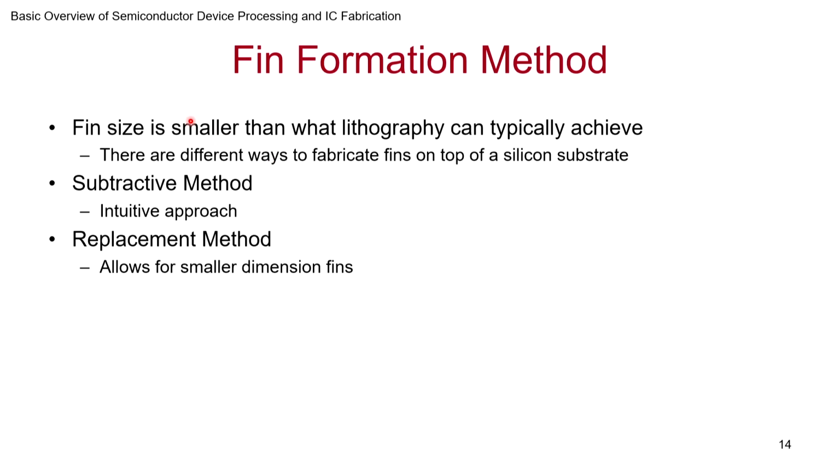Okay, so now we saw the basics of the FinFET, and I hope you will be able to recognize a FinFET when you see one and understand what is happening, where the source is, where the drain is, what the gate is, and so on. Now let's look at one aspect of the FinFET. The fin is one of the most distinct features of the FinFET, and it turns out that you want to make it much smaller than what lithography will allow you. So what do you do? There are lots of tricks people use. Of course, you try to push the lithography limit as much as possible. That's one way, but you could also use other tricks.